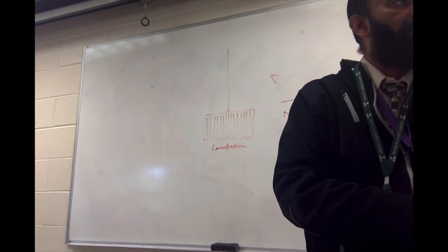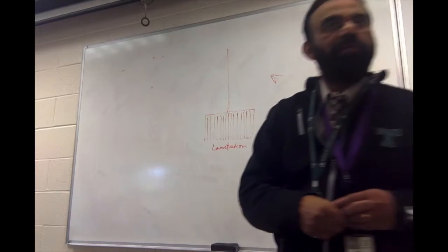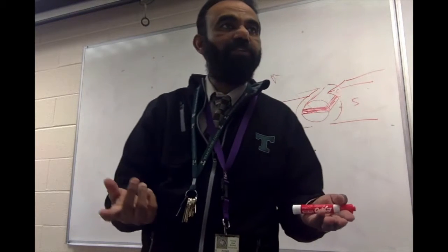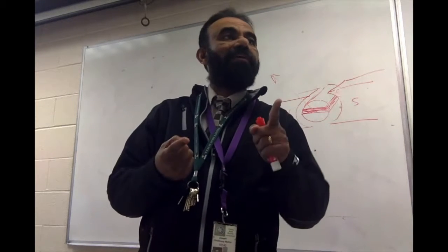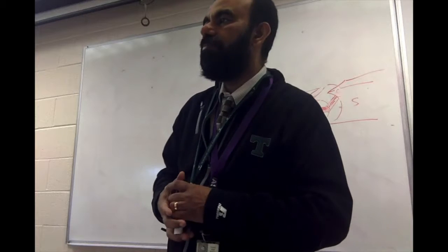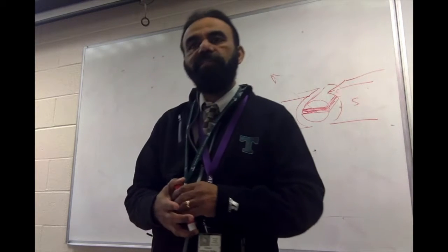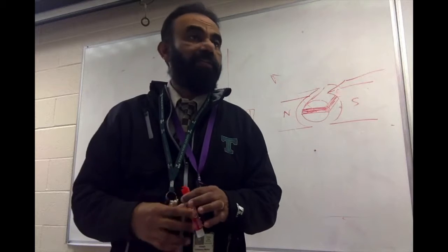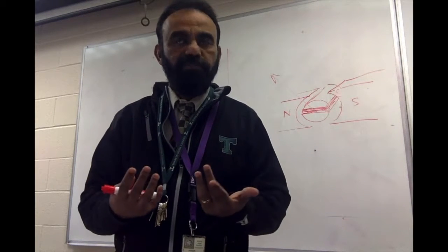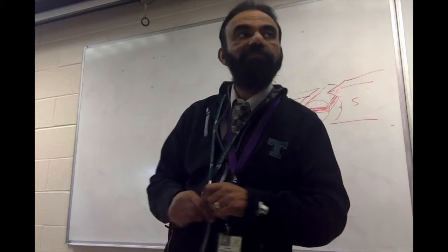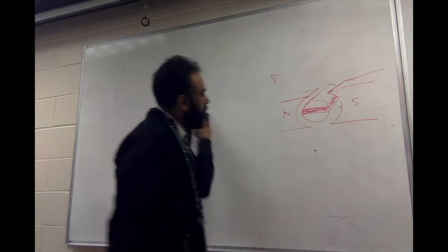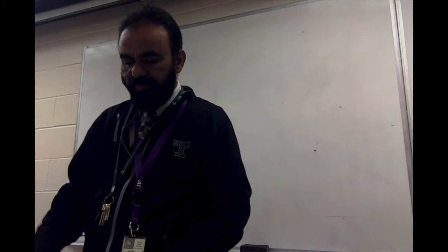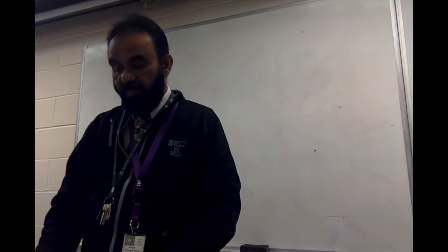If you have a motor with just a solid core, the purpose of the motor is basically to spin, right? Now, the very spinning action produces eddy currents, which will be counteracted. So therefore, it will not spin as fast. If something is spinning in a magnetic field, you need to make it spin freely without the eddy current effects. So you can see the laminations, how it is done. Okay. So the purpose of lamination is to reduce the eddy currents.